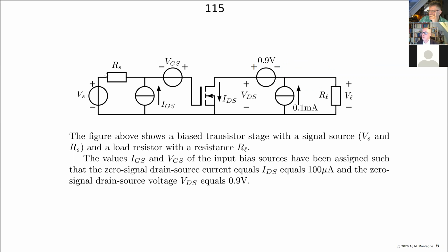So now a negative voltage, which means that the transistor will turn off, which means that the current will, well, if there is still a little bit of current through the transistor, it will flow like that from minus to plus. Let's say the transistor doesn't turn off completely, then there's still power dissipation here, although it decreases with decreasing the input voltage. And here we originally had no voltage, but now we have a positive voltage here. And you see it is flowing from minus to plus through the device. So this is delivering power now. So it means both are delivering power.